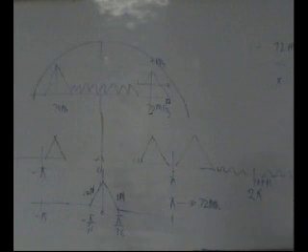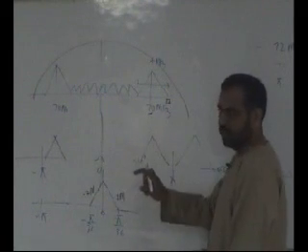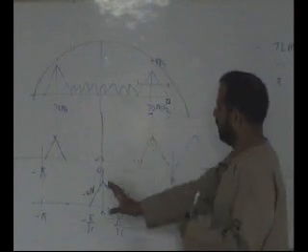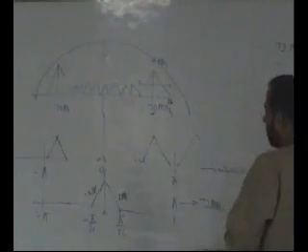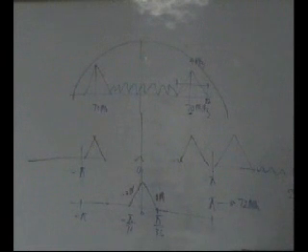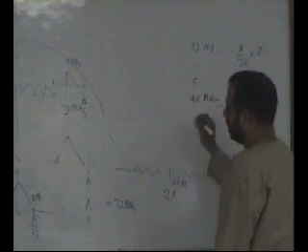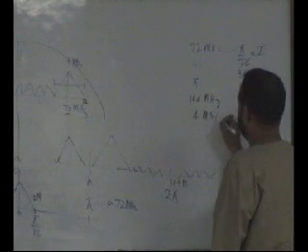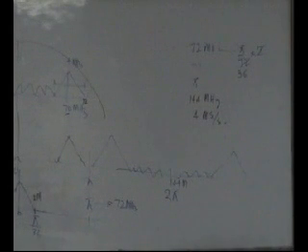Now remember that once you bring the spectrum here at the baseband, at this point we really are not focusing on how you bring it, but we can bring it down by multiplying it with an exponential to shift in frequency. So you bring it here, and the signal has been sampled at 144 megahertz, and you really only require how many mega samples? 4 mega samples per second. So you are keeping a lot more samples than what is required.